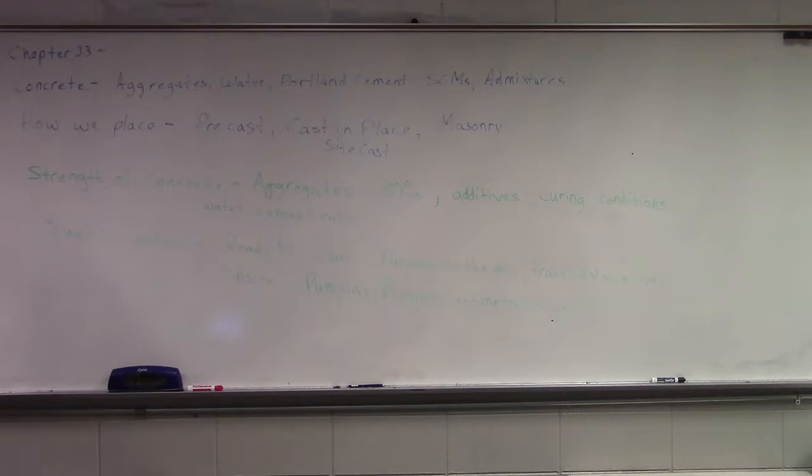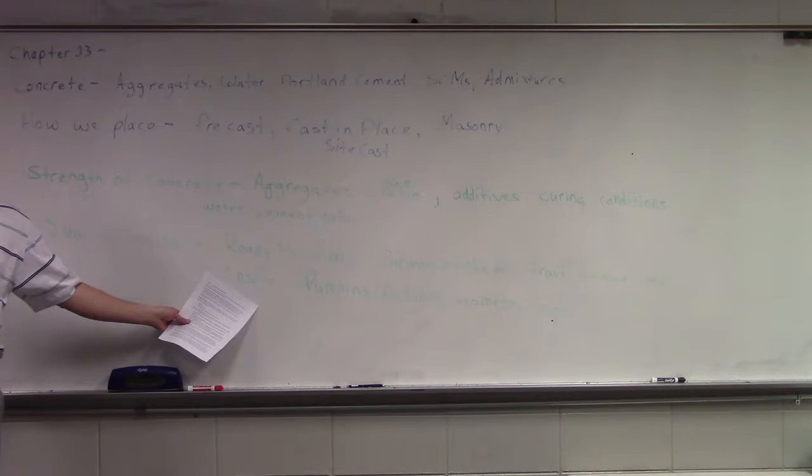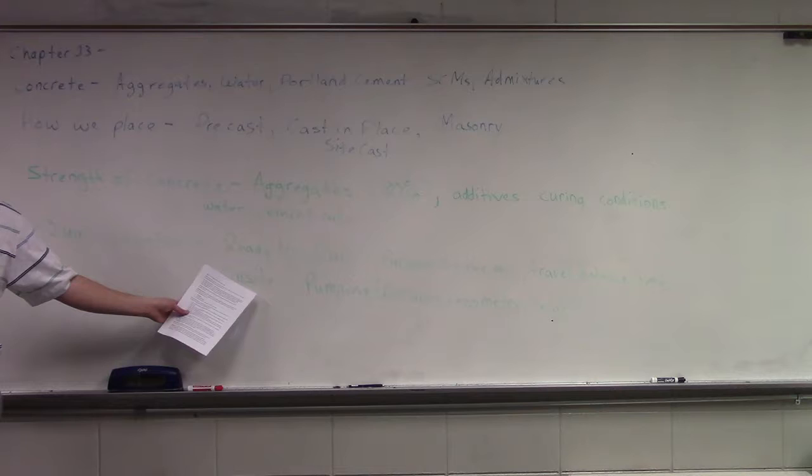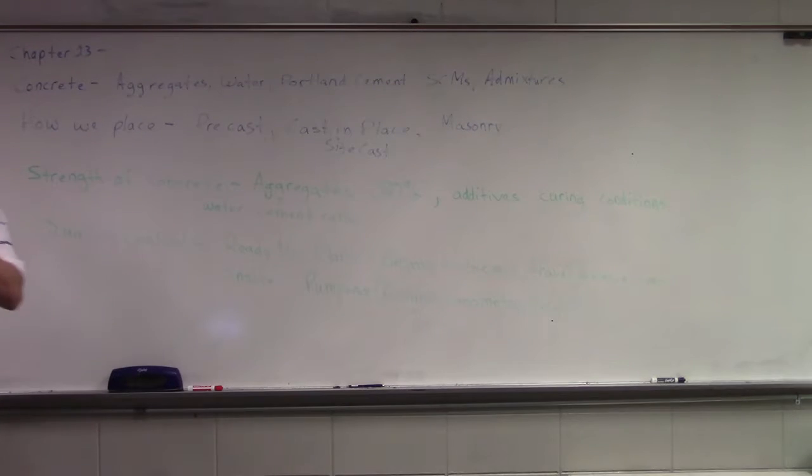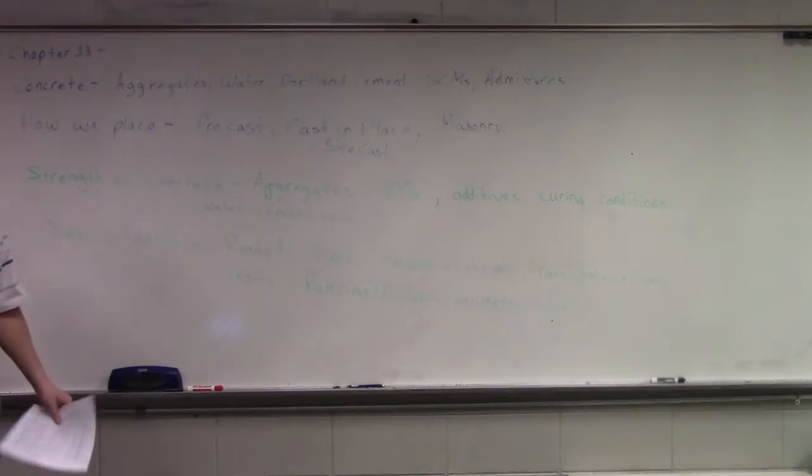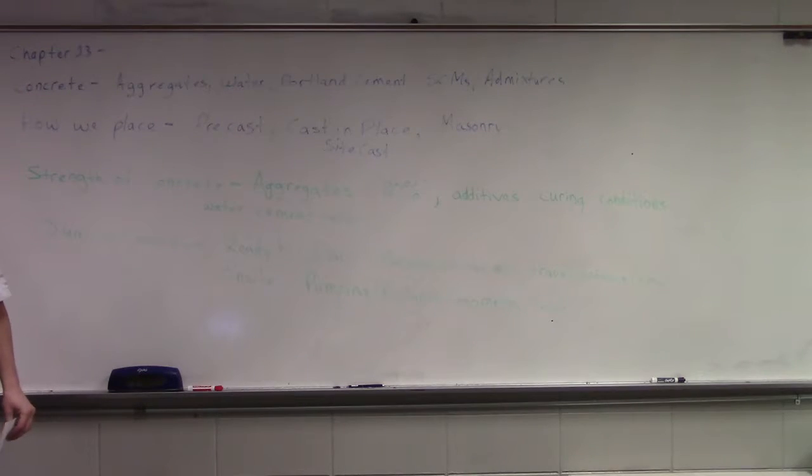We tried and tried and tried to figure out how we could pump onto that bridge deck, and we just couldn't do it. It couldn't both meet the requirements that the state had and be pumpable, so they conveyored all of that concrete onto the bridge deck. I wasn't up there for much of the pours. I'm sure it was a huge pain in the rear end to place that much concrete with a conveyor. So yeah, pumping absolutely gets to be a very big issue.